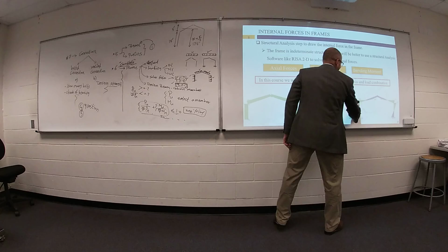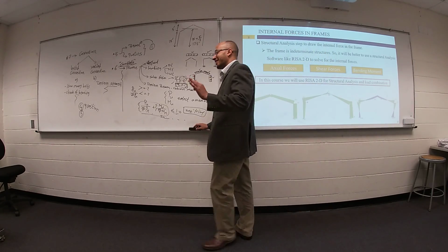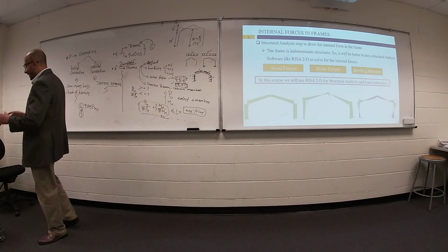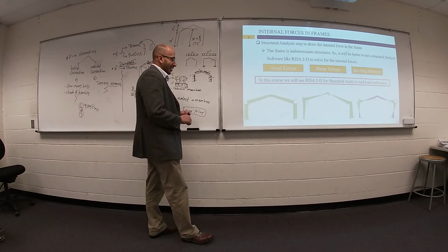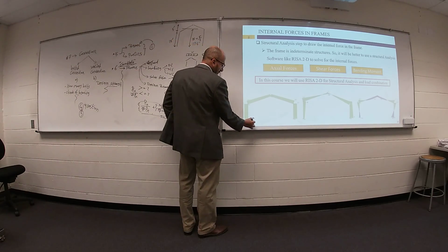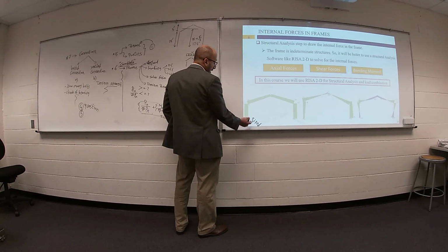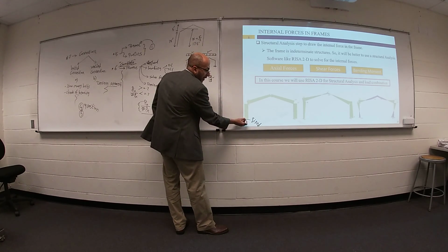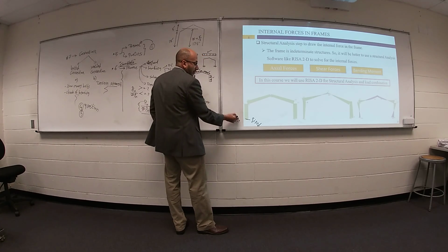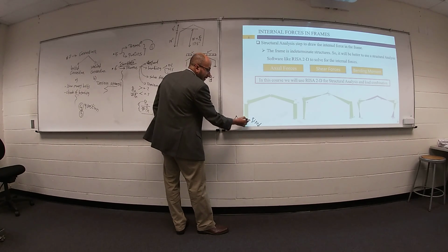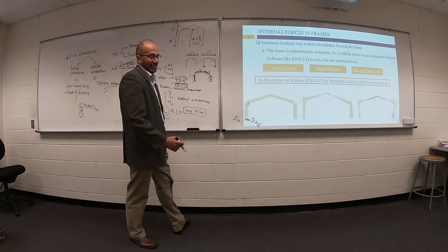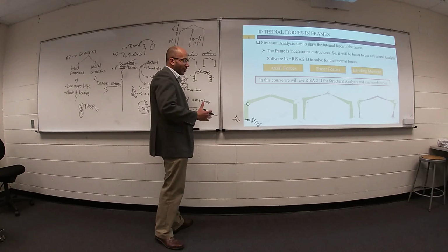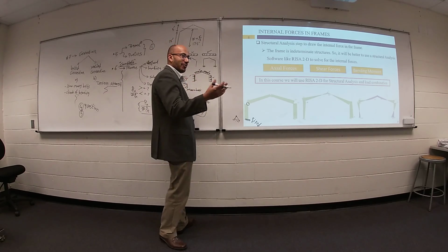Good question. It's not clear what the end condition of your column is. As you define your support, if you define it hinge, it's hinge. If you define it fixed, it's fixed. What about the other condition? It's not clear, it's not hinge and not fixed. Something in between, but we will assume it fixed.